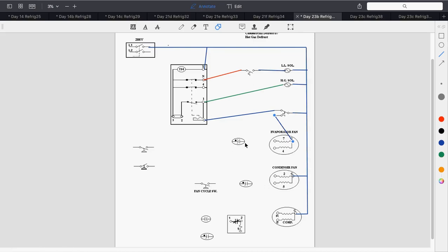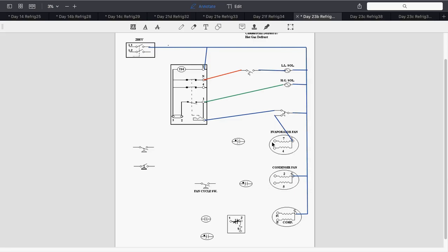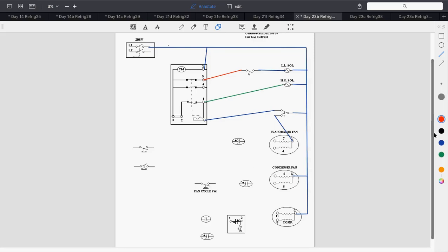What type of capacitor is this? It's a run capacitor. Yeah, so what does it go in series with? With the run winding? Start winding. Oh, start winding. Again, we don't ever want to put a capacitor in series with the run winding. Now, a lot of times you see the other side of the capacitor is used as a junction point.